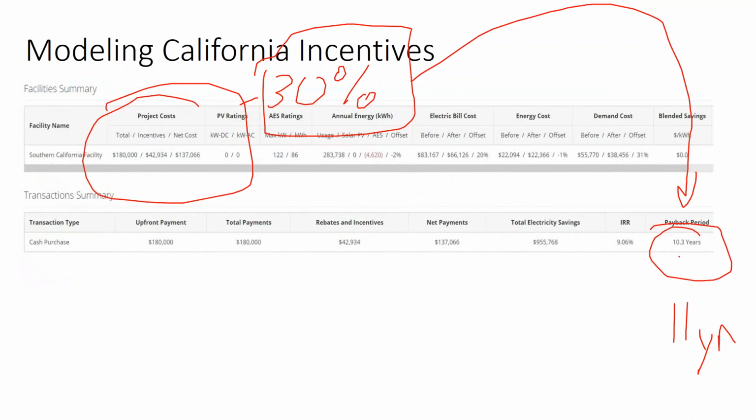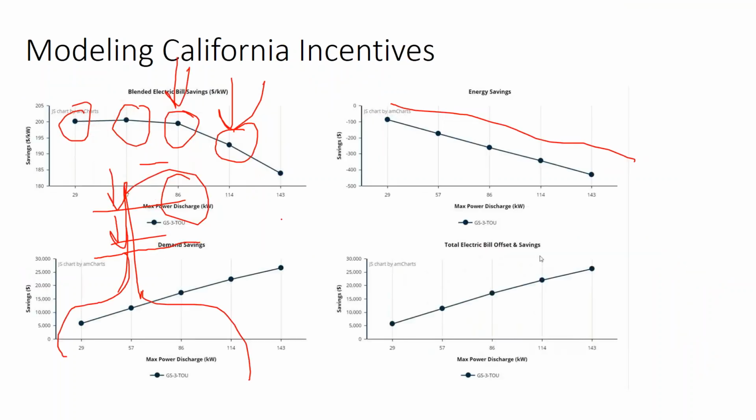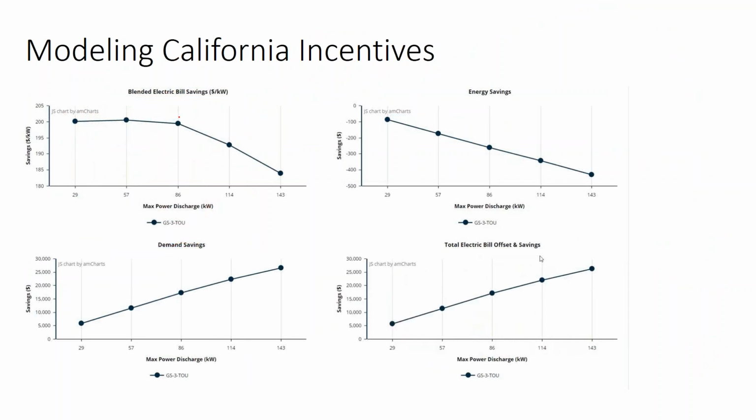effectively, adding solar to the battery will do two things. One, it'll qualify the battery bank for the federal tax credit. That'll drop this 10-year payback down to about 7 years. Two, it'll allow you to get further into this load leveling curve, whereas with batteries on their own, you might only be able to get so far into it. But by adding solar to take over your building demand management in the middle of the day, you might be able to get a little bit further into your demand management before you get into diminishing returns.